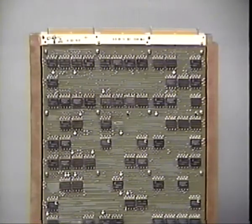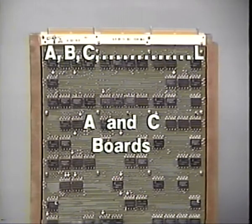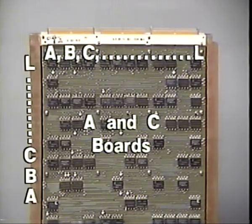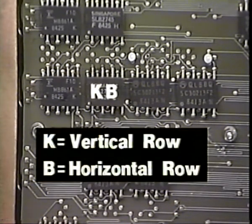To locate individual chips on a board, a chip coordinate system has been devised. On A and C boards, the horizontal row of chips is labeled A through L. The vertical row of chips has also been labeled A through L. As an example, this chip is at coordinates KB, K being the vertical row designator, B being the horizontal row designator.